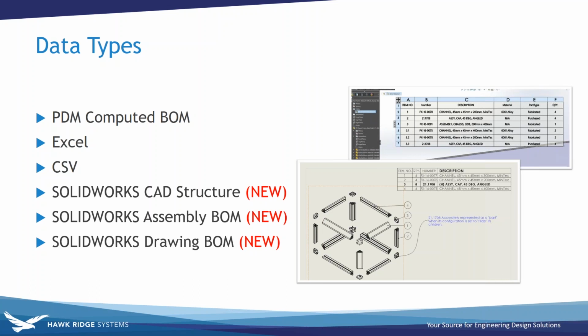If you look at that drawing bill of materials image there in the slide, it's got 4 items listed there. One of those is an assembly that is used as a part. So that's a commonly used hide feature, or option that we enable in the configuration properties of our assemblies. But there's another one called promote that is commonly used when we need to assemble things in an assembly file in SOLIDWORKS, but we don't want them to show up as an assembly in a bill of materials.